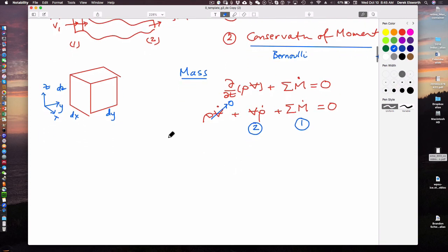And so what we can do is we can write this in terms of a velocity in the y direction that goes in here, a velocity in the y direction that comes out of here, which is dv dy times dy. And if we write sum of mass flow rates is equal to 0, then we can write this as the area times the density times v, right?